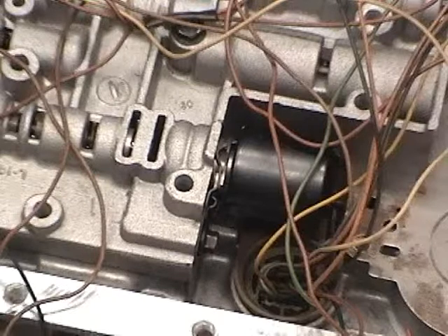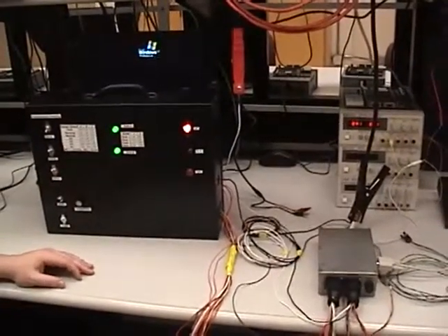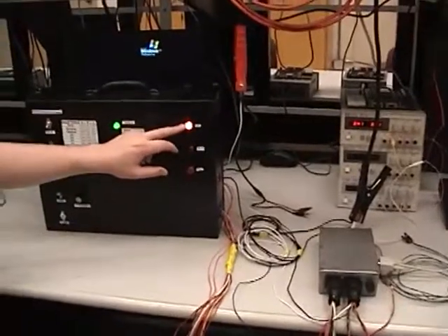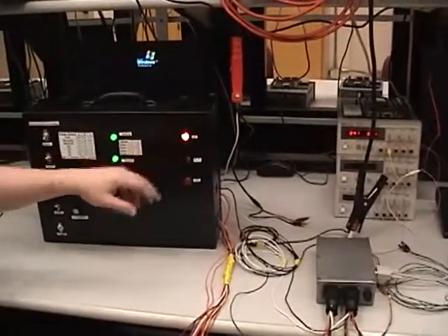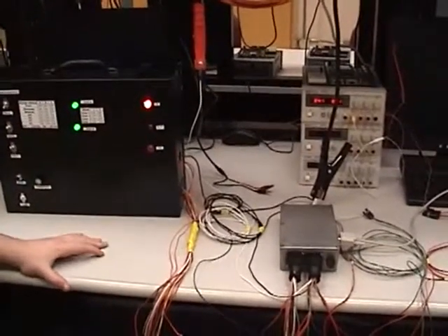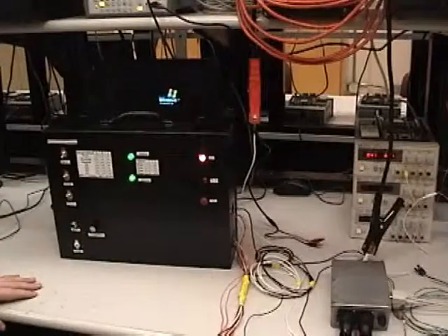Since it's normally on, a low PWM duty cycle, so this light being off, would represent the highest line pressure that you can have. And then as we send a larger and larger signal to it, say 60% duty cycle, the maximum, you'll see this light brighten to its maximum potential, and that's simulating the lowest line pressure it possibly can have.